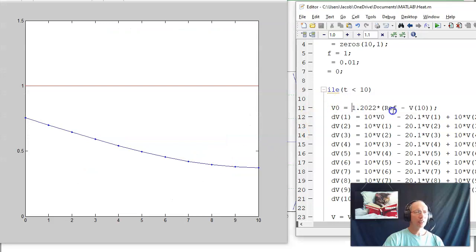So make that 5.3217. That's my gain compensator. Now what it should have is initially the voltage goes to 5.2 off the screen, then backs off. By applying more heat, it warms up faster. But I get overshoot. And I should have 20% overshoot.